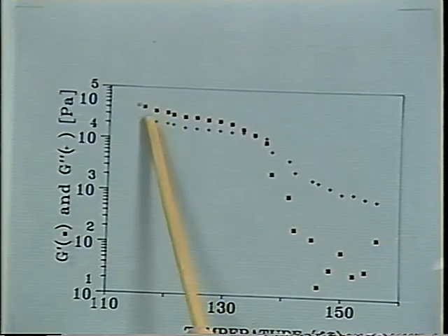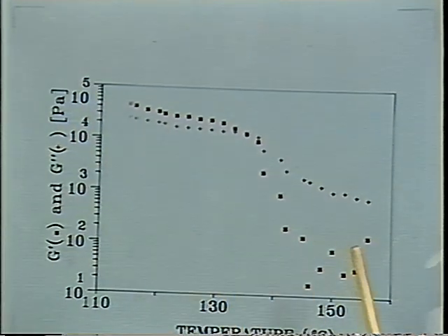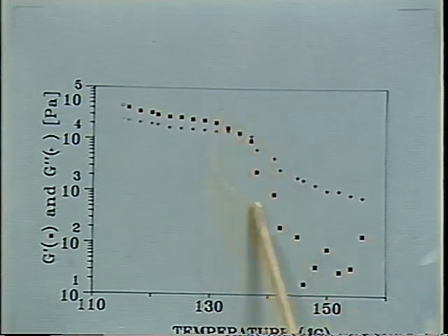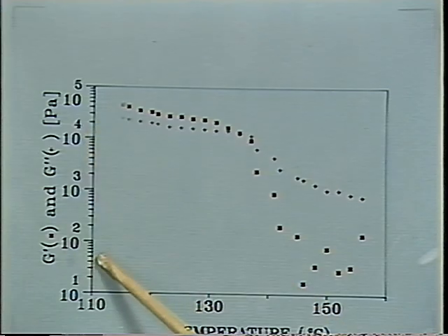If you would continue that to go below Tg, there would be another rise here. So it's a melt. Both phases are molten in this system. Only due to phase separation, you have a drop in the modulus. You can see that the drop is very serious. It's several orders in magnitude as the sample homogenizes. The rheology can be seen most drastically at low frequencies.